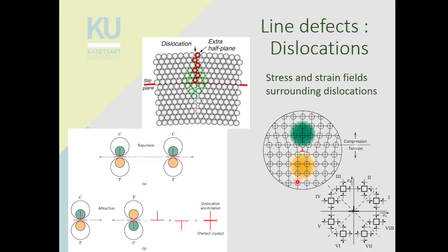You have a lot of residual stress within your lattice, right? And when you heat it up in the stress relief process, all the atoms here will try to arrange themselves into a more perfect lattice, like the rest of the area, right? So you will get rid of this strain field around the dislocation.